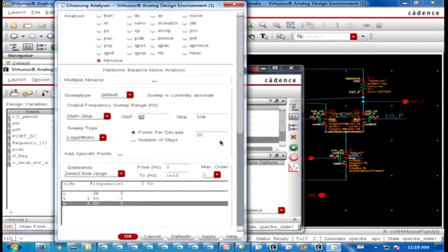And then I have to go for a harmonic balance noise because I have to calculate, or at least parameterize, the noise figure. So in this case, to calculate or know about the noise spectrum, you have to sweep and capture the range which will be included by the intermediate frequency band, that is the IF band. So I don't have to go for RF sweeping, rather I will go from some low frequency to 50 megahertz because I know 2 megahertz is my IF band. And then again I have to select a range of frequency, but I have selected here just 2.5 gigahertz for the first band.